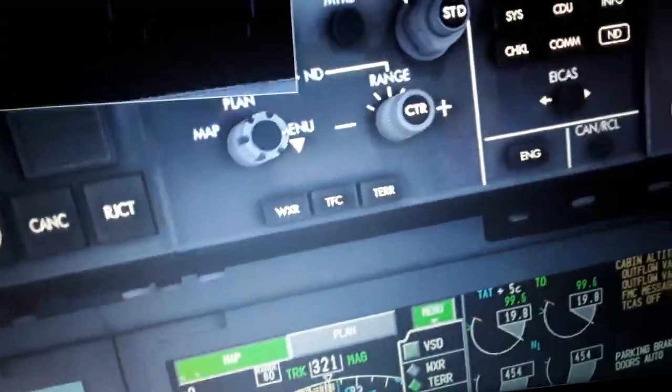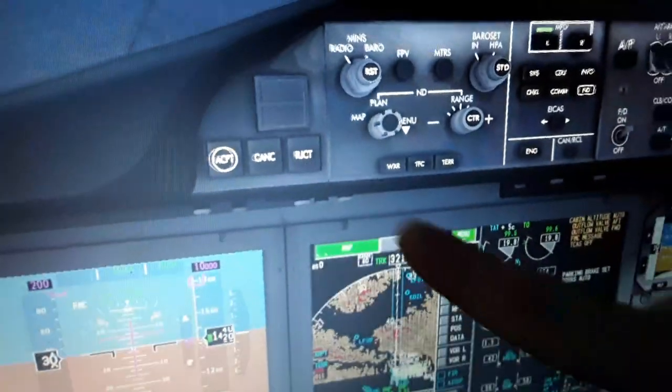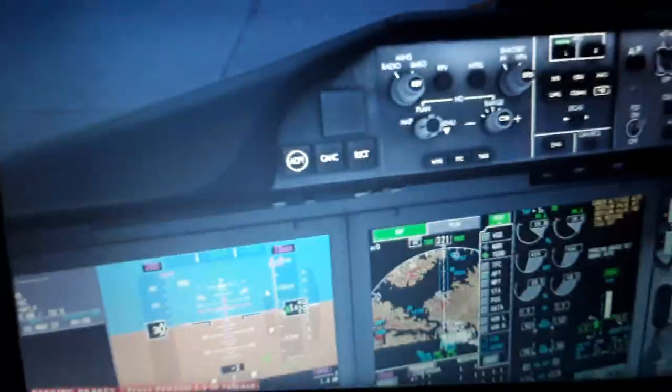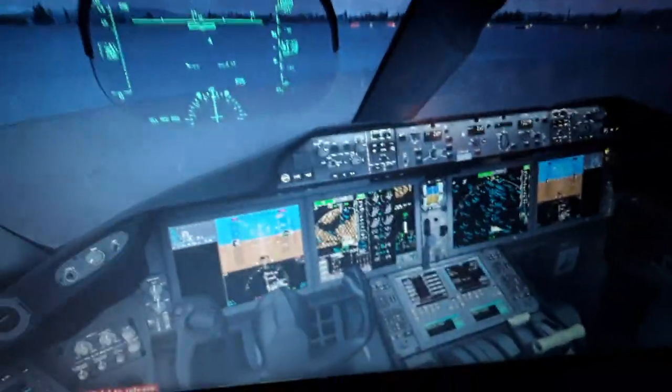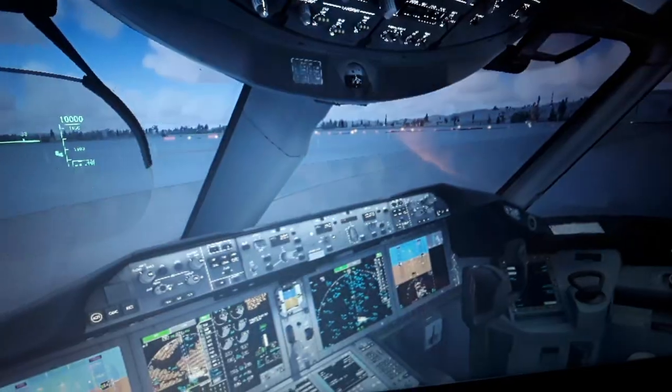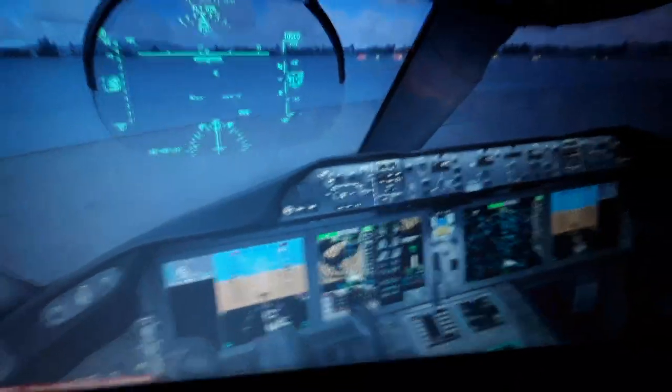We have the weather radar over here, WXR, traffic and the terrain, all this displayed here, and the barometric altitude here for the altitude display. So you will see all these things. You can see also all the air data. We have pitot static, pitot dynamic, airspeed, altitude, GPS position, magnetic, north pole heading, or are displayed using the air data computer here.